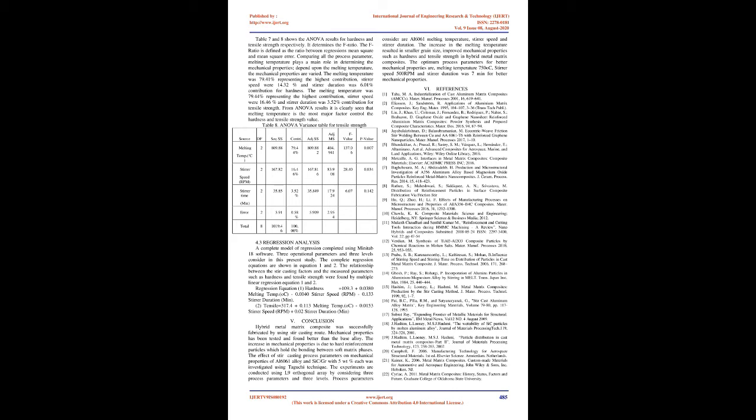Hence, the optimum level of process parameters is the level which has maximum S/N value. Fig. 4 indicates the response curve in S/N ratio. The highest tensile strength and hardness was observed at larger-the-better S/N values, Figs. 4 and 5. The optimized process parameters for hardness and tensile strength are stir pressure at level 2, melt temperature at level 1 and die temperature at level 2.